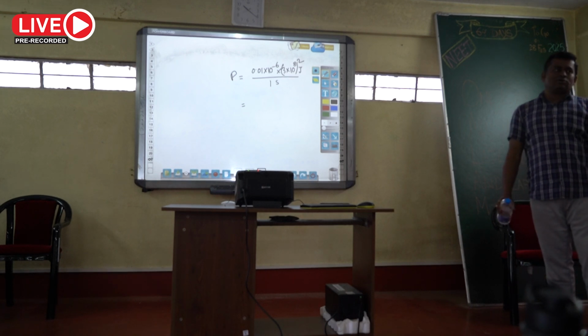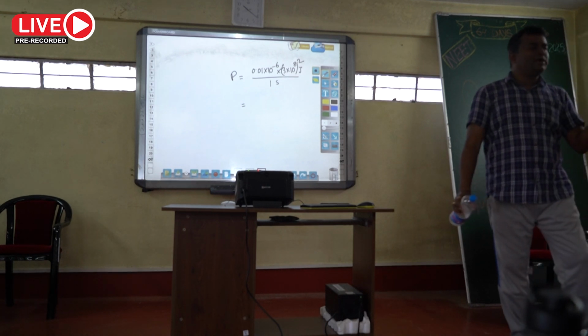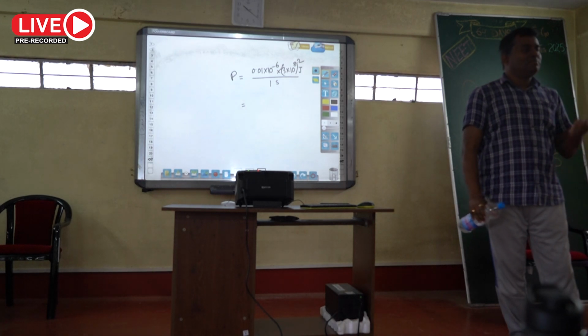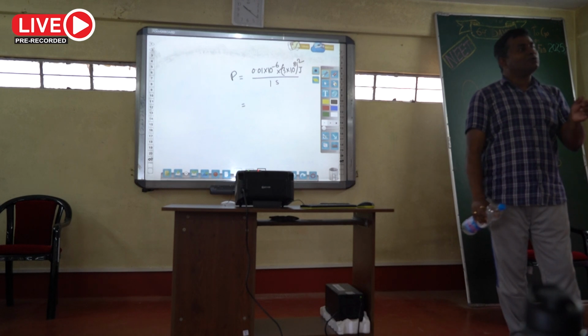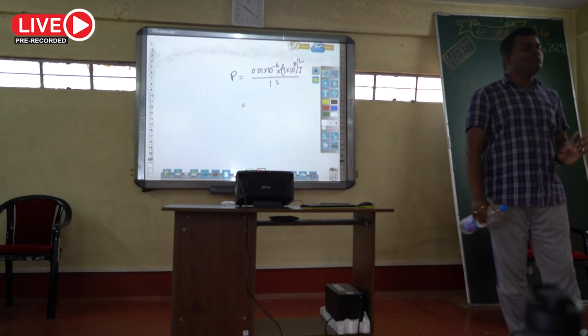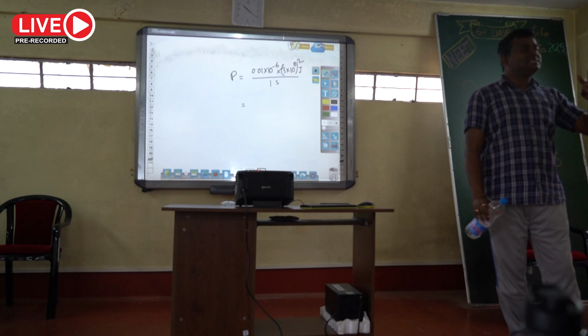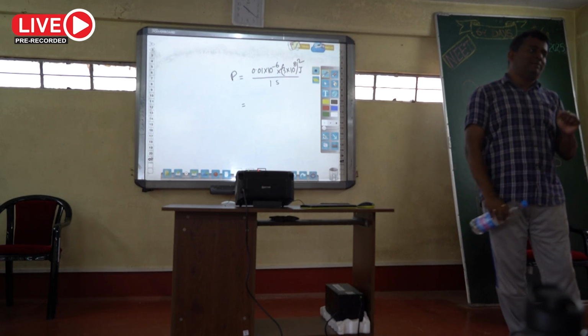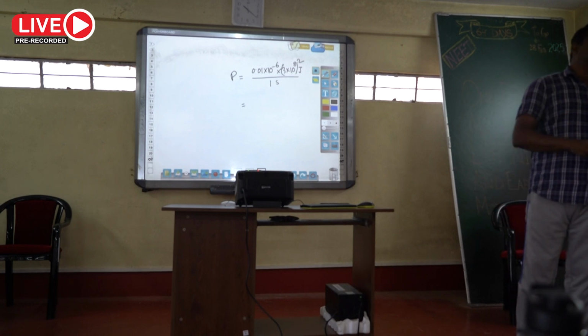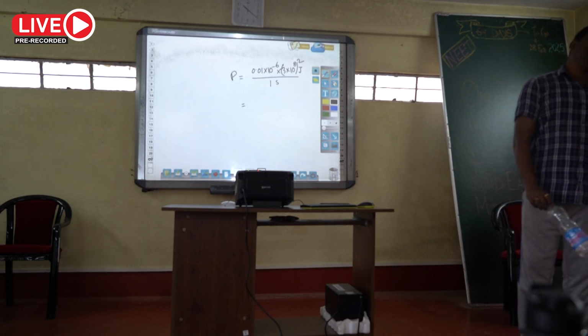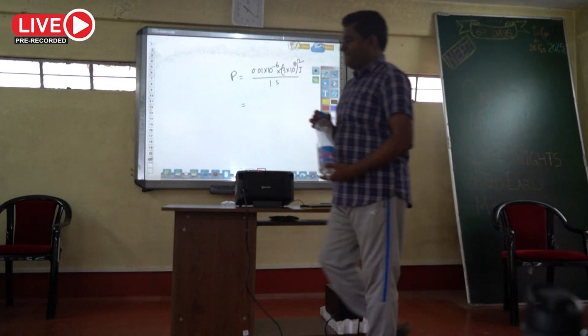At 0.3, silicon will not conduct. But when the silicon diode has a voltage of 0.7, then it will conduct, and not only that, germanium also starts to conduct. But since they are in parallel, the voltage across both of them is 0.7. So 12 minus 0.7, that is 11.3, will be the answer in that case.